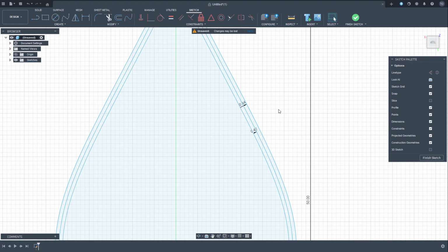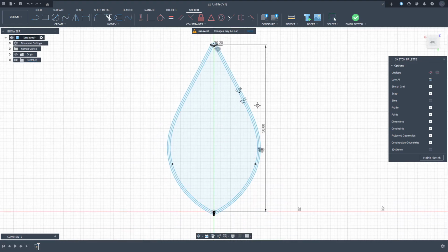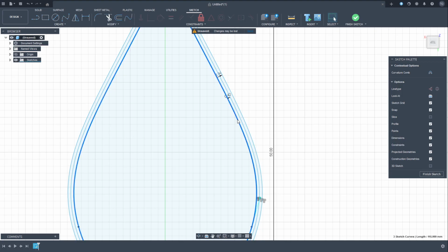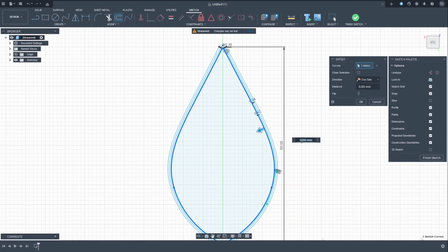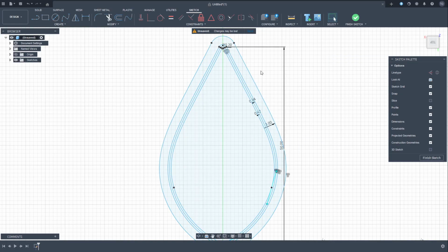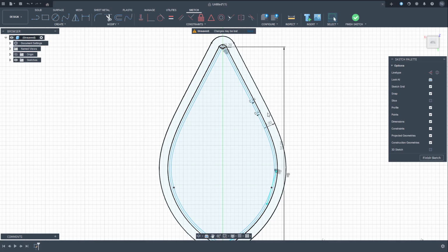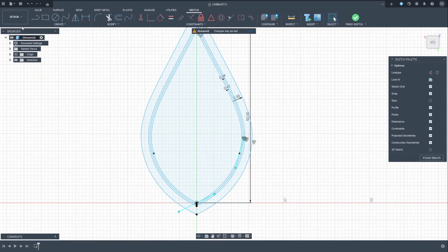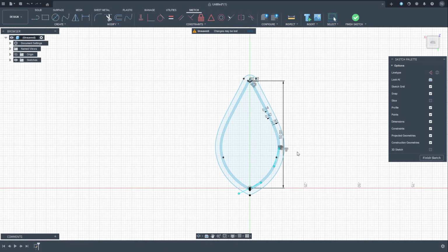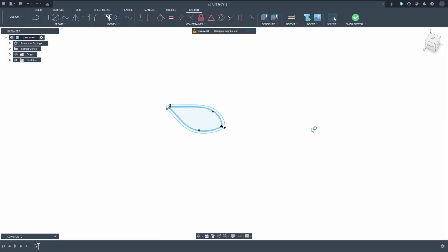And there's one more thing we need to do in this sketch. We need to do one more line, so one more offset, and we're gonna call it -3. Okay, so that will give us a place to hold the cutter from. So when you work with it, you can just have something steady and sturdy to grab it from. Okay, so now we're done with the sketch. We finished with all the sketching things, and we just say finish sketch.